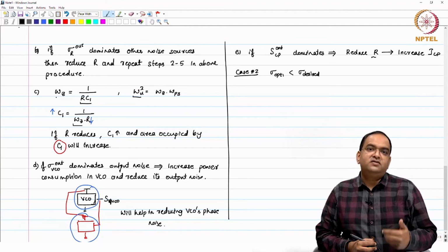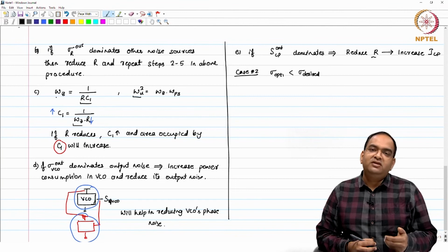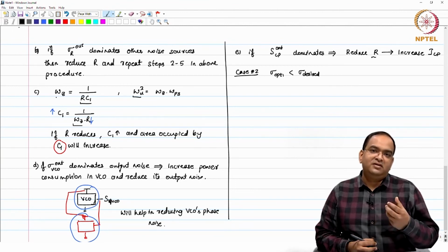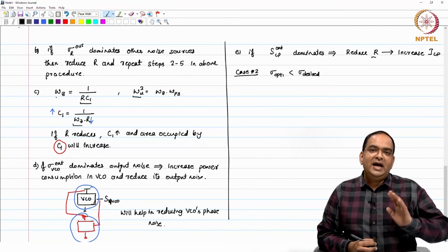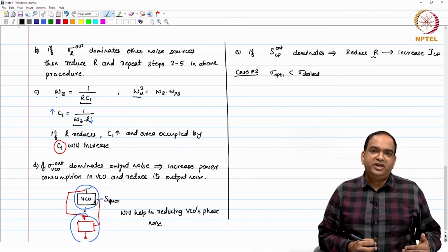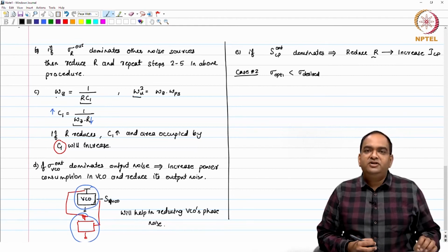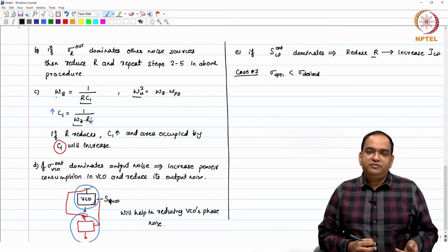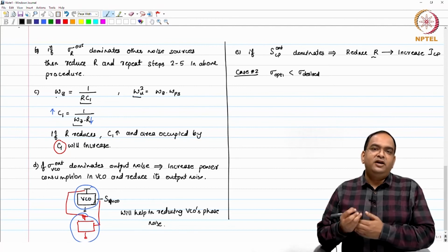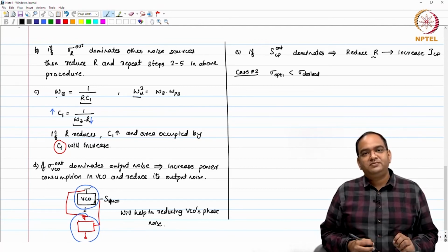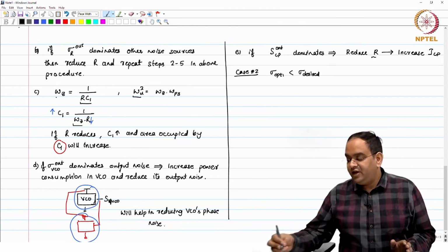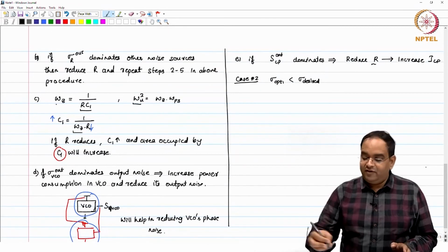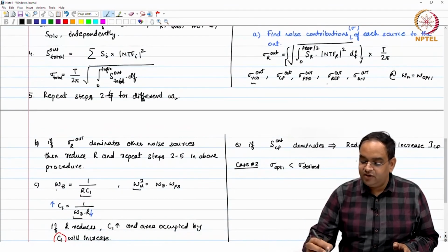If your jitter is lower, then by default you can think about it that your power consumption in the design is larger. Okay. So, it is like I need 2 picoseconds, I am getting 500 femtoseconds, right. So, I am spending power for 500 femtosecond, but my requirement is not 500 femtosecond, it is only 2 picosecond. So, if I try to get 2 picosecond of jitter, then I can reduce my power consumption.